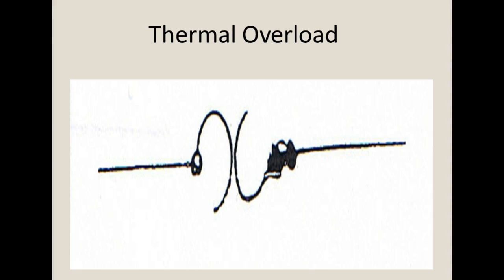Now, fusible link, I probably ought to take off. We just don't see it anymore. We'll get to this, but I used to have one I couldn't put my hands on. This is a heater. We'll flow electricity and amps through this heater. It'll get red hot and give off heat. That's what strip heat is.